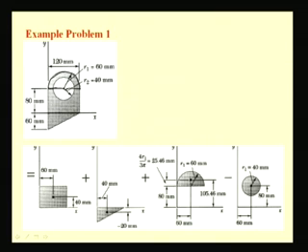And if we consider this semicircular lamina, it has an axis of symmetry. So, its centroid lies at 60 mm from the y axis, which is equal to the radius of this semicircular lamina, and it is located from its diametrical line at a distance of 4r by 3 pi, which in this case is 25.46 mm.